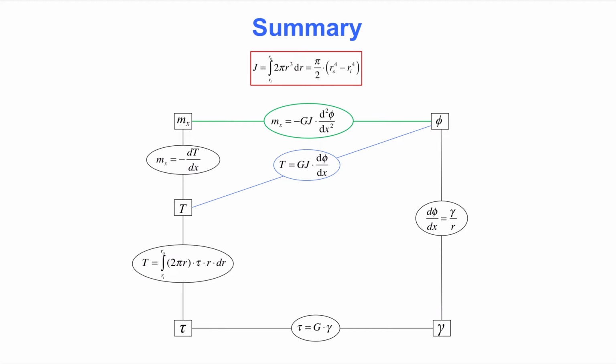They are also combined in order to obtain the differential equation for St. Venant torsion, marked with the green color. Notice that the cross-sectional constant for St. Venant torsion for members with a circular cross-section is defined in the red box. The equation that combines section integration, material law, and kinematic compatibility, but omits equilibrium with externally applied distributed torque is also derived, shown in blue.